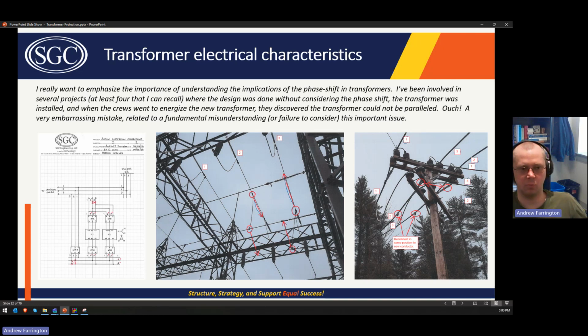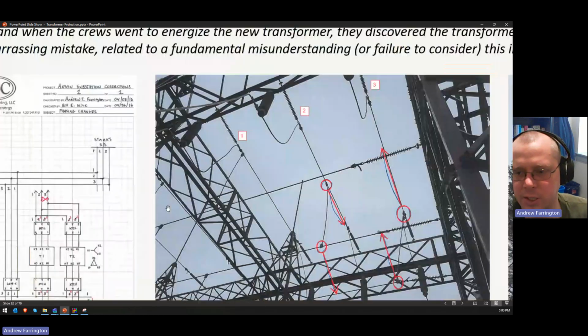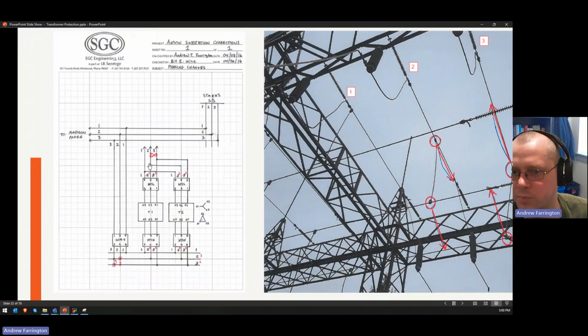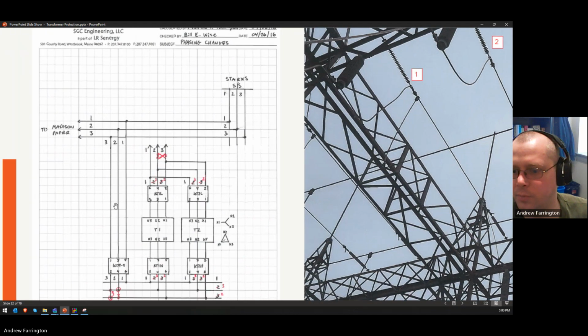And so we were working with them to come up with an outage sequence plan so that they could take their substation out of service, make the changes while minimizing the impact to their customers. And they said that they actually had a tie switch that tied their 34 kV system, which is here, over to a local utility.